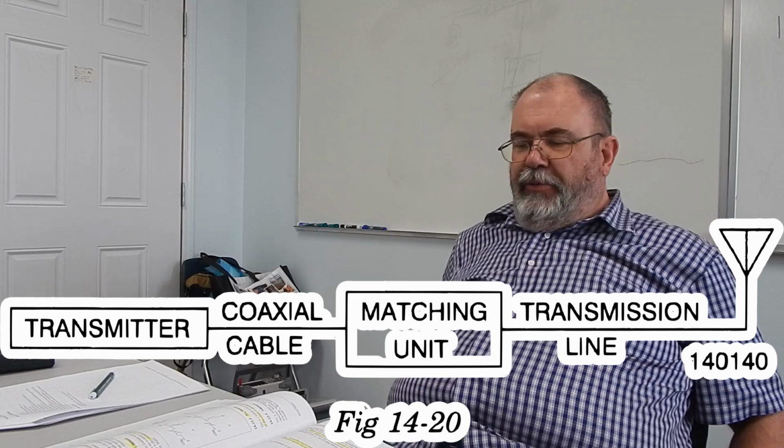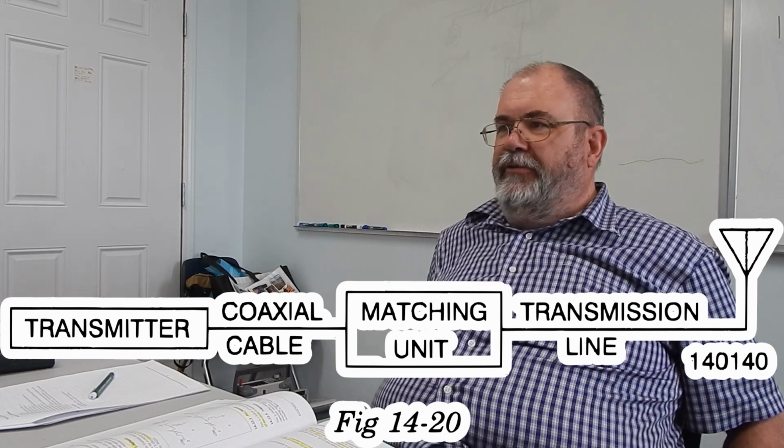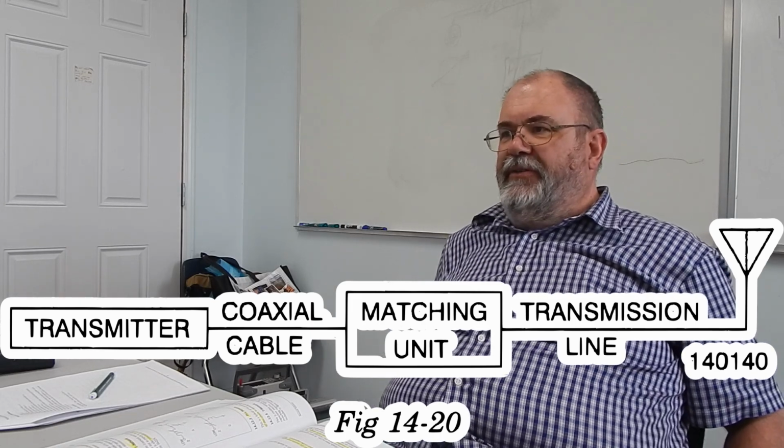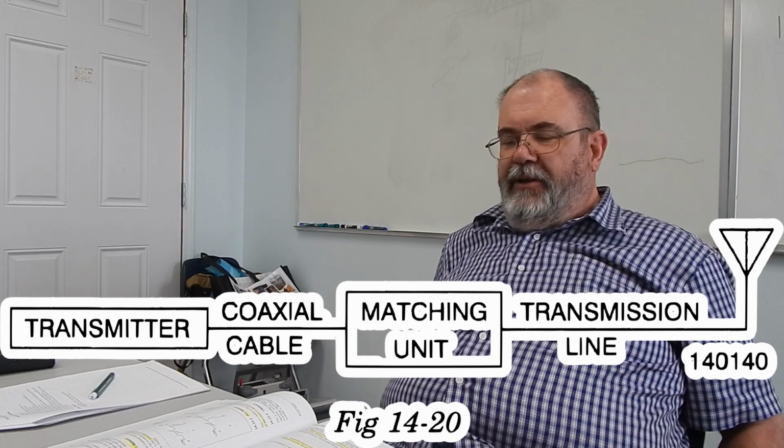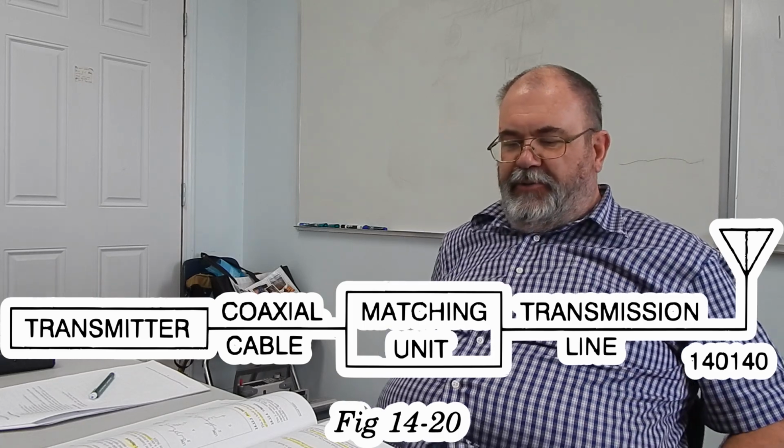And as we know, when we put up an antenna, there's always stray capacitances and stray inductances and stuff that we cannot really avoid. So we can tune it out. And there's various kinds of antenna tuner they talk about there on the page. One is called a transformer antenna tuner, and a transformer is exactly like when we talked about power supplies with a primary and a secondary winding and all that kind of stuff.